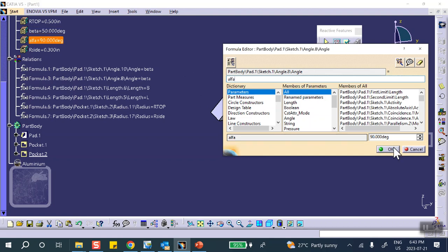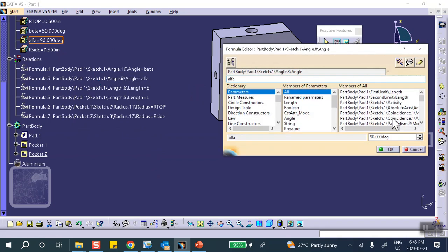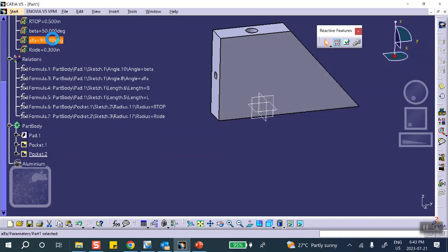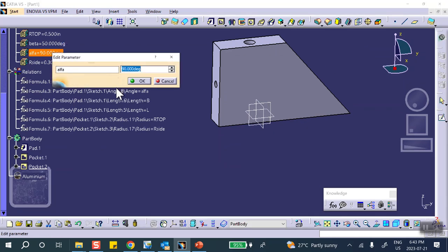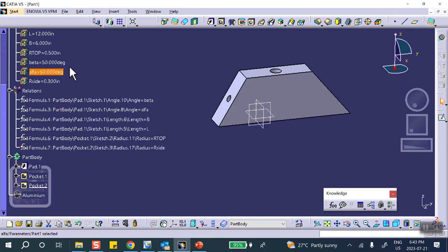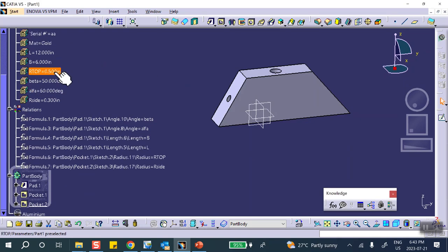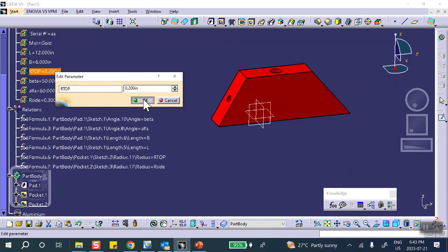You have to do these patiently. There. Okay, so let's put it back from 90 to 60. 60. Check the radii on the top and the bottom. Our top right now is 0.5, so let me make it 0.2. It's going to become smaller.